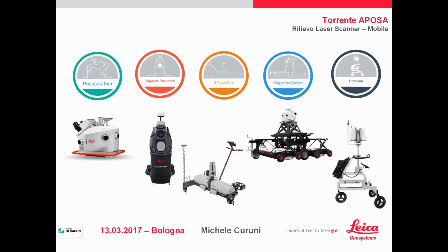Why did I not choose the backpack? Because the noise of the point clouds was too high, because the 2 scanners that you see here are running at 25 or 30 meter distance maximum, and the error can be over 1 centimeter.